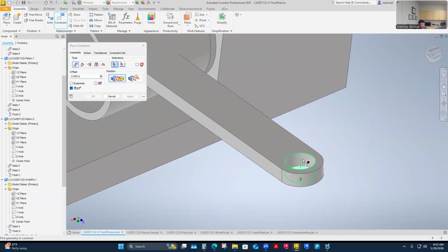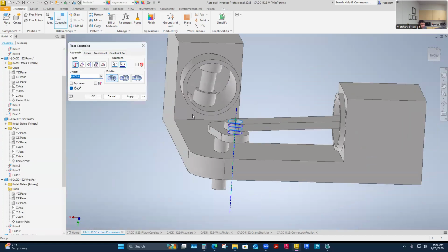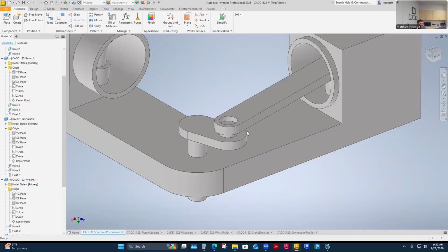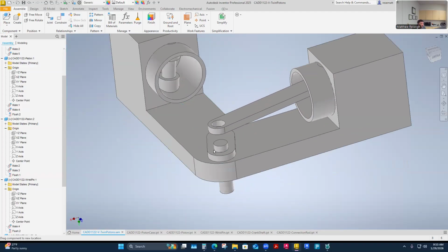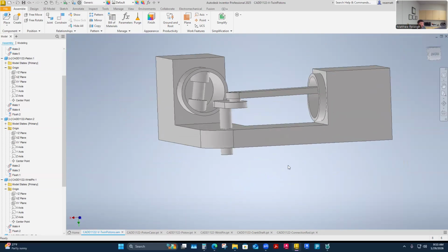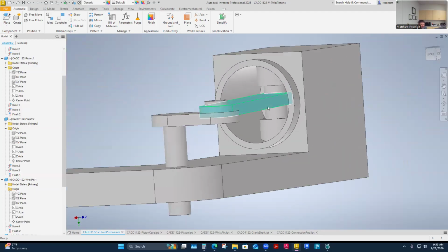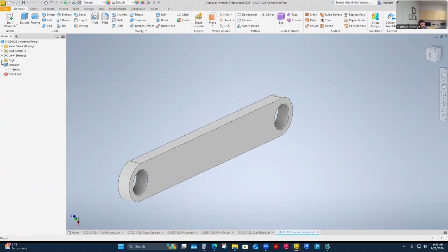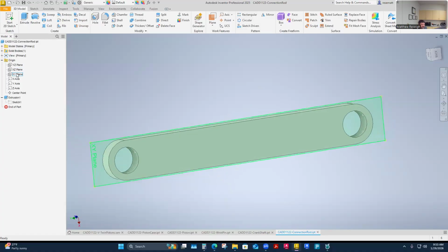And then I'm going to apply this next hole, axis to axis here. And that snapped in good. I'm going to say okay. I did them both. Yeah. So right now I have axis to axis, but it can really go up and down. You're going to stay aligned in some ways. I think what I did now though is I definitely did. I don't know how yours is built here, but this is another one that I adjusted on my original part. So I'm going to say open this one up back to this one. Just check yourself. I want to use its origin planes as well. So it's centered that way, it's centered this way, and it's centered this way.